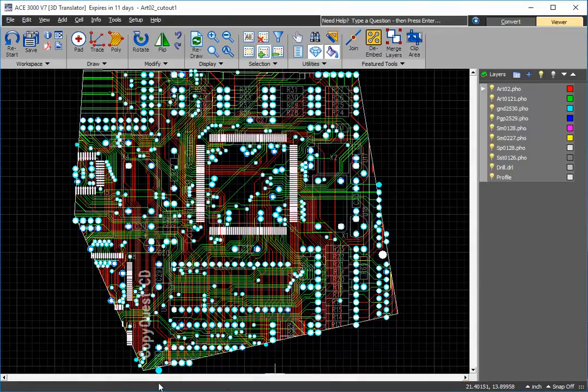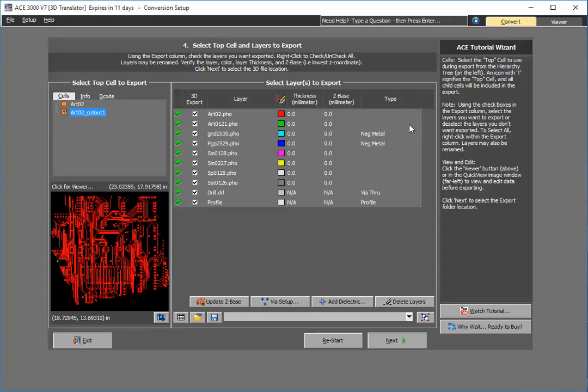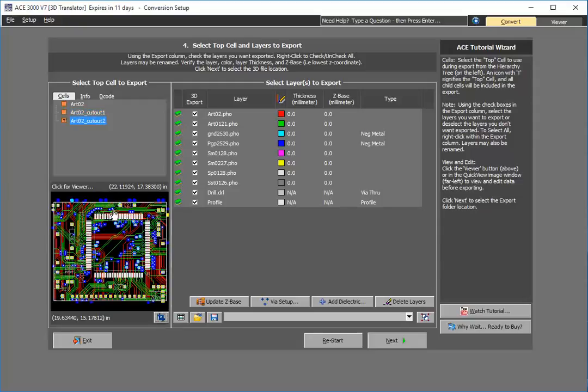And as you see here, all the pads that touch the clipping area still remain existent. And this is because for many calculations and simulations, they do require to have the net with the entire amount of metal still available. So what I'll also do is show you how to use clipping directly from here, which is even easier. You just select a square. You just basically choose your area and the clippings automatically perform for you.